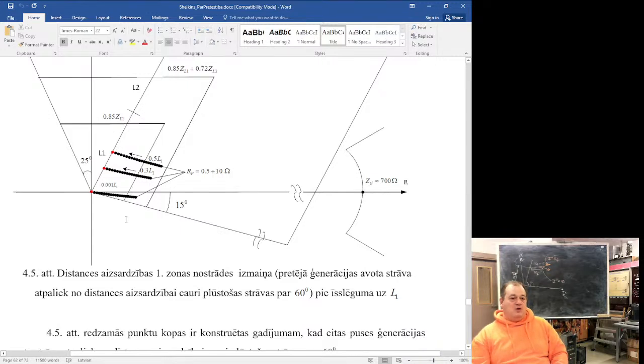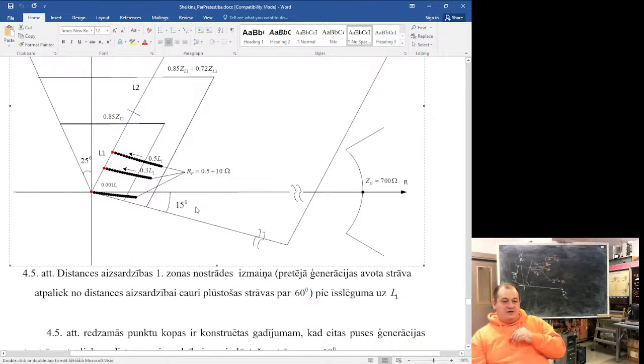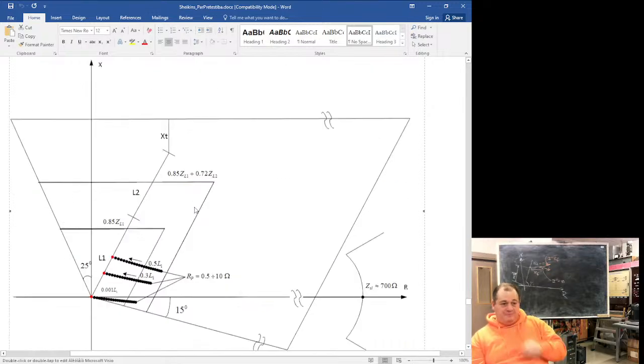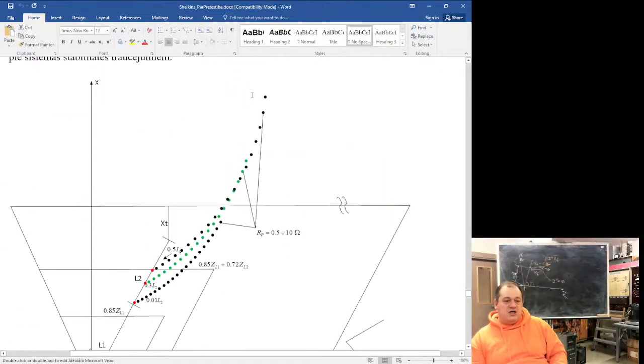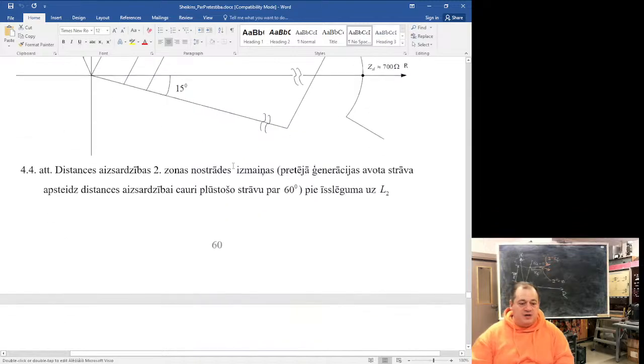Exporting mode. We are exporting energy. See? Now we have kind of negative. In case we are importing energy, transient resistance has a positive imaginary part, going outside of the protection zone and causing delayed operation.